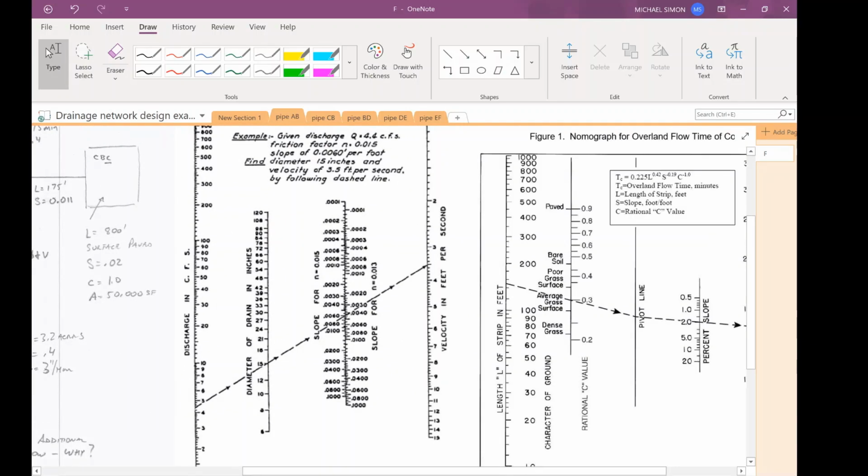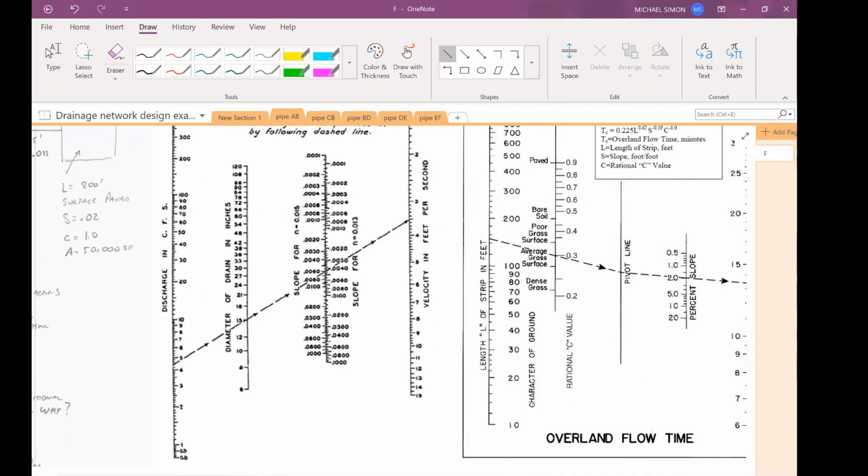So, moving over to the nomograph. 5 and 5, Q of 5, and a velocity of 5. And again, it's a lot easier doing this on paper than on a computer screen, but we'll try. 5 and 5. Okay, perfect. So that's 5 velocity and 5 for my Q. Remember on the nomographs, Q is here, velocity's here, that's my slope, that's my diameter.